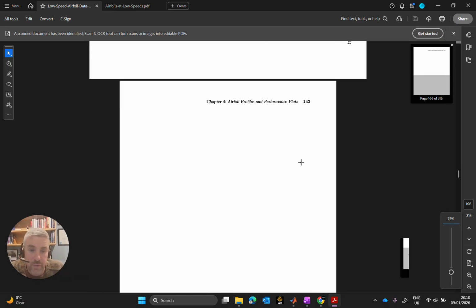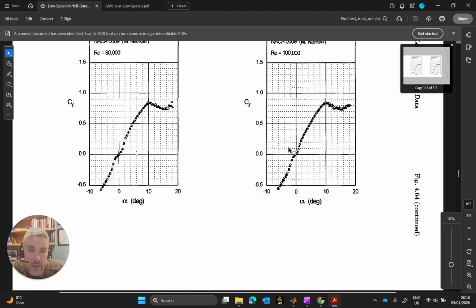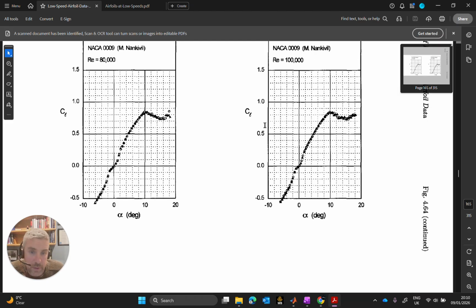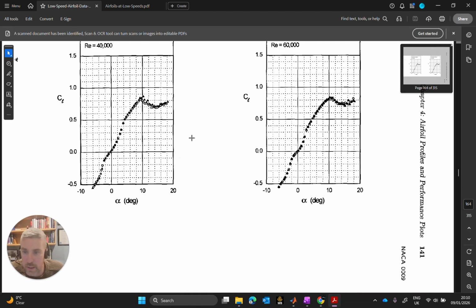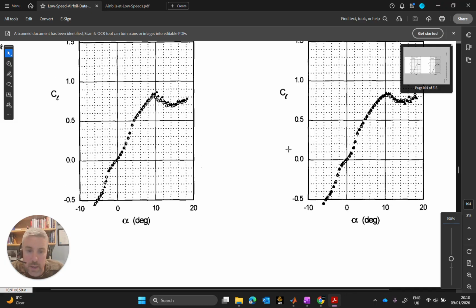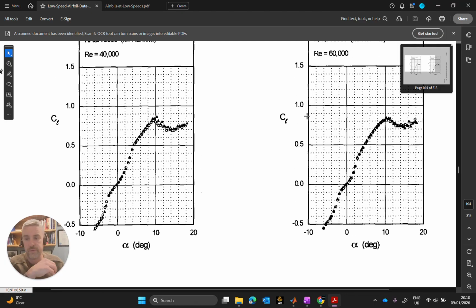Now, right enough, where's the drag? We're not seeing drag on this here, but that's okay. All we're looking to do is get confirmed test data at a Reynolds number that we can test using our model, our solver, and our wall functions for the laminar flow regime.